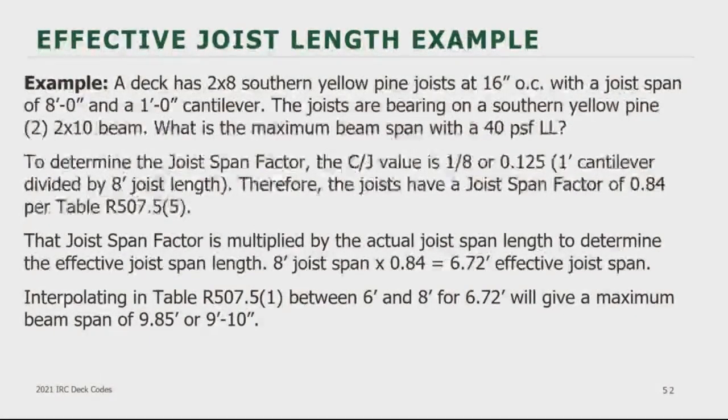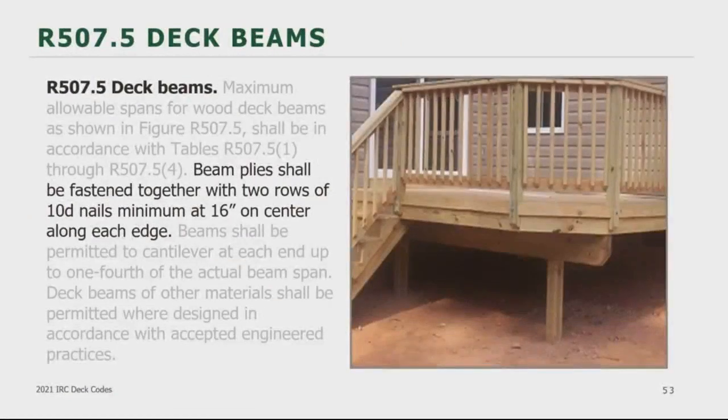All right, let's jump back into R507.5. Often beams on a deck are done with multiple plies. The code gives you requirements for how to connect those plies to make sure that they act as one beam as opposed to individual boards just sitting there next to each other.